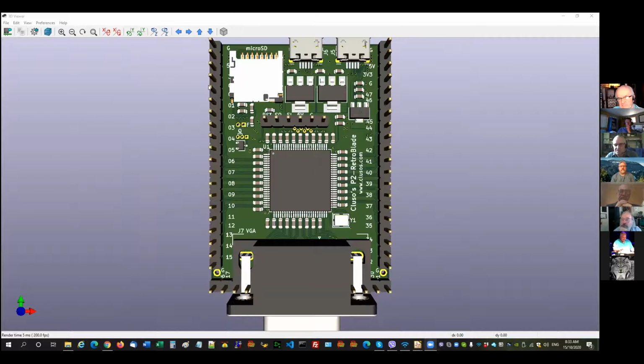So now what have we got with our I/O ports? We go from 0 all the way down to 15 down here, and then we've got a ground sitting in the middle, which you typically won't put on, and then you come across here. So the left-hand side's got 20 pins to there, miss one, and then we go across here. If you want to just file that down slightly, you can actually go 20, or you can go 22, and then you can go across here 14, if you want to actually fit all of them.